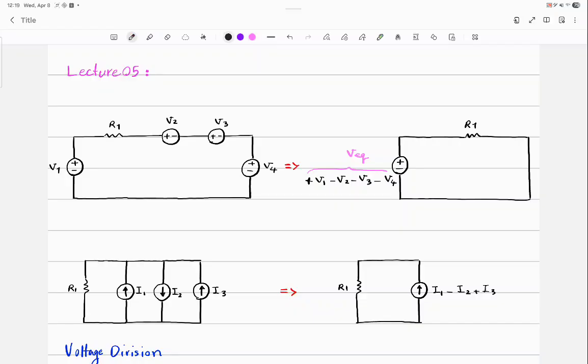If you don't see that, I am asking you to do this. Mentally, move that to where you can align it with the way your equivalent voltage is. Like this. Is it in line with the equivalent voltage source? No, it's exactly opposite. So that appears with a negative sign. What I do in my head is move it and bring it close to V1, so they are all following each other, and then say, okay, this is not like my equivalent. So it comes with a negative sign.